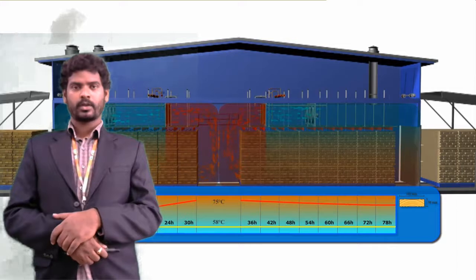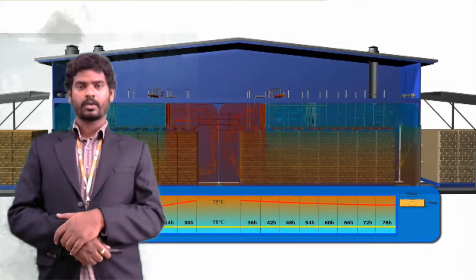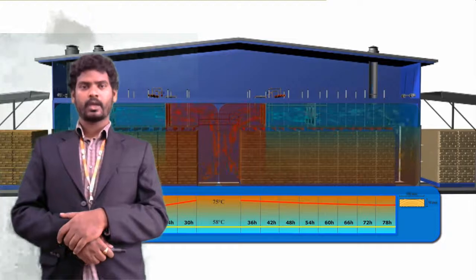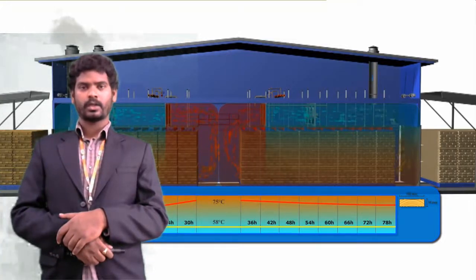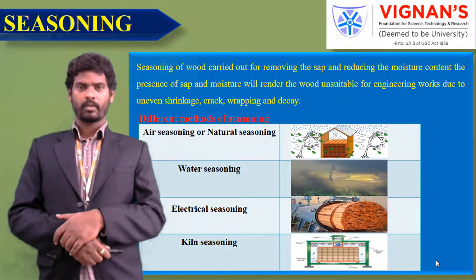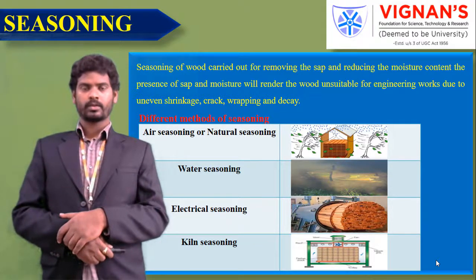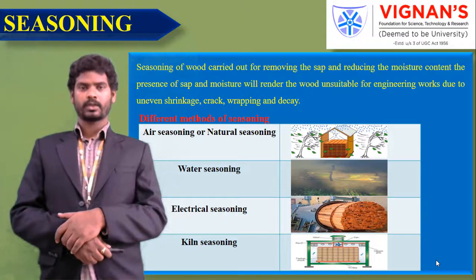The ventilation is provided to avoid overheating and excessive humidity. The timber inside the chamber on trolleys is kept under controlled conditions for about a fortnight, depending upon the initial water content and required moisture levels.